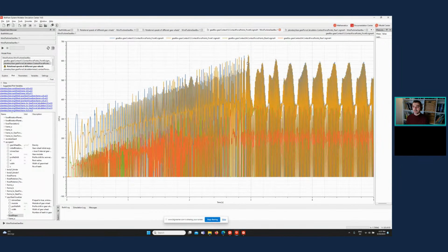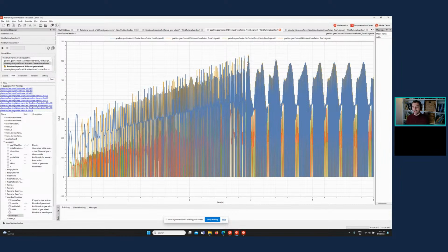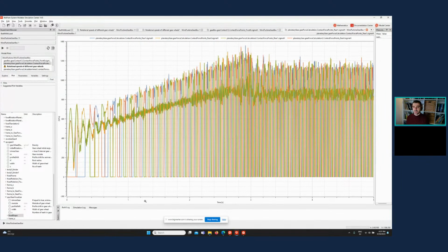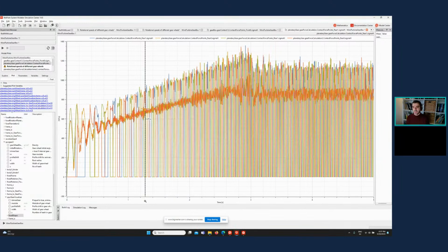We can either look at stresses or even forces, so all is possible, but looking at the stresses at this level is more beneficial compared to looking at the forces, because just by judging the stresses you can say that this gear material, this design, at least, is within the allowable limit and won't cause any damage even if I run the dynamic simulations.